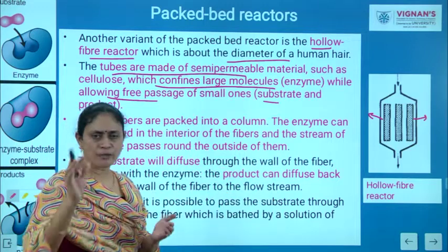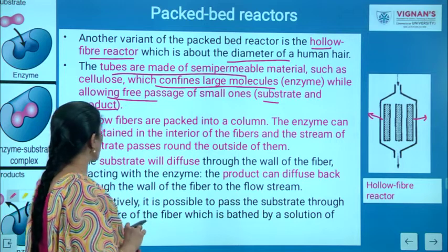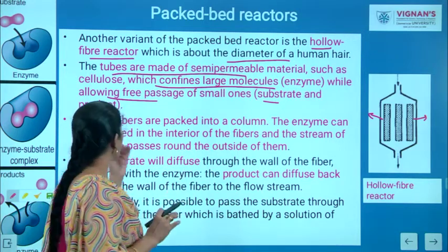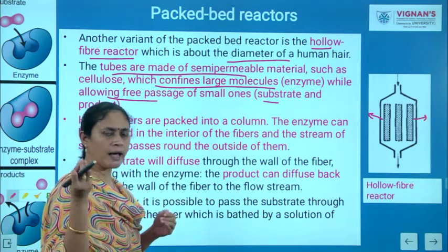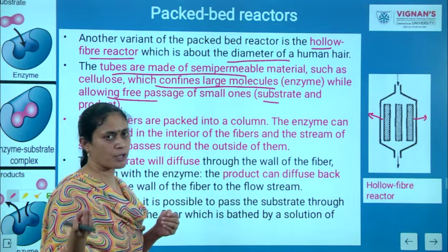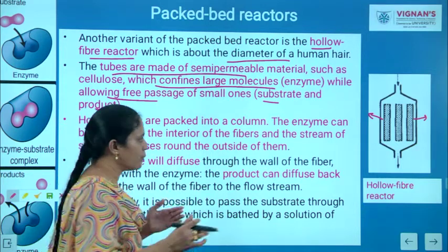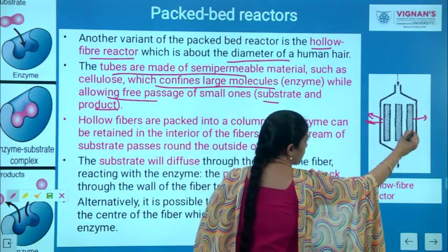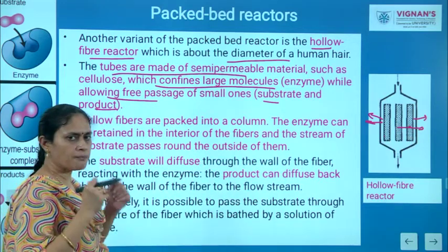The other modification of this packed bed reactor is nothing but your hollow fiber reactor. What is the importance of this hollow fiber reactor? We have considered a number of fibers which will have a diameter equal to the diameter of your human hair, and we are placing a series of these fibers inside the reactor. These are nothing but your fibers. So you have incorporated a number of fibers into your reactor.